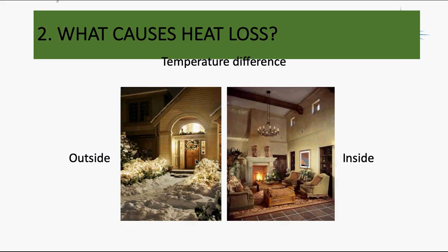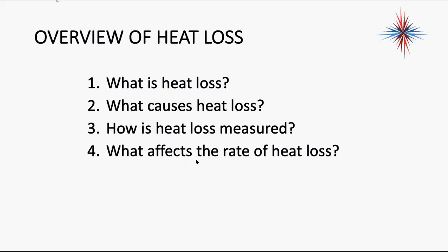Heat loss is caused by a temperature difference, okay? If my outside is cold and my inside is warm, I obviously have a temperature difference. I talk about it on a future slide, but my heat loss grows with the temperature difference. So if I have a 20-degree temperature difference between indoor and outside, I might have a certain amount of heat loss. If I suddenly raise that temperature difference to 50 degrees, that heat loss is going to get bigger. Heat always flows from warmer to cooler. So temperature difference makes a big difference.